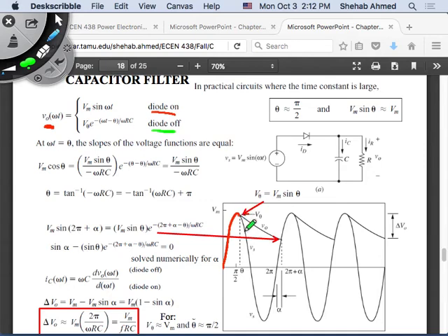Because the supply current is falling and the capacitor is in parallel, assume you just have a supply and a capacitor. If the supply is in parallel with the capacitor and the supply voltage is falling, what does this capacitor need to do? It needs to discharge to the supply, if there's no resistor connected. As soon as it tries to do that, the diode blocks.